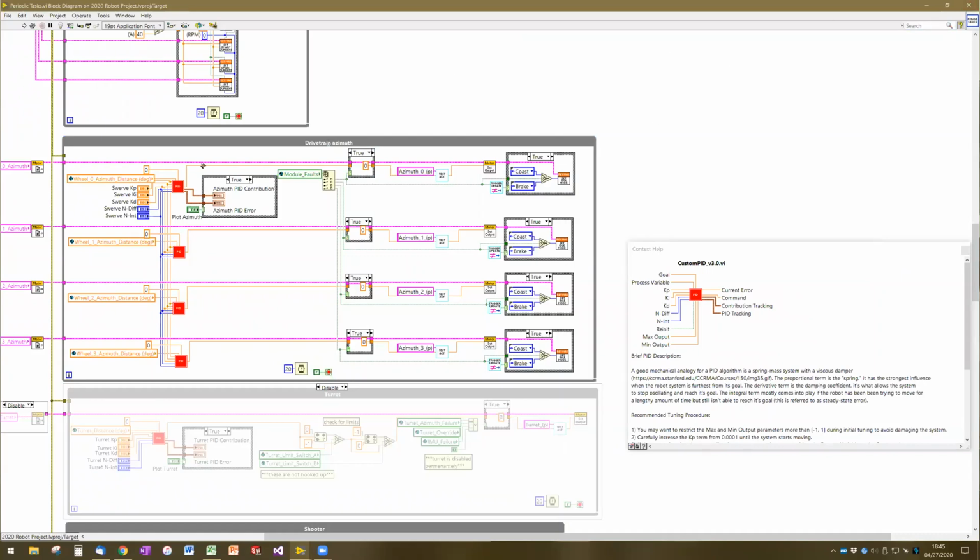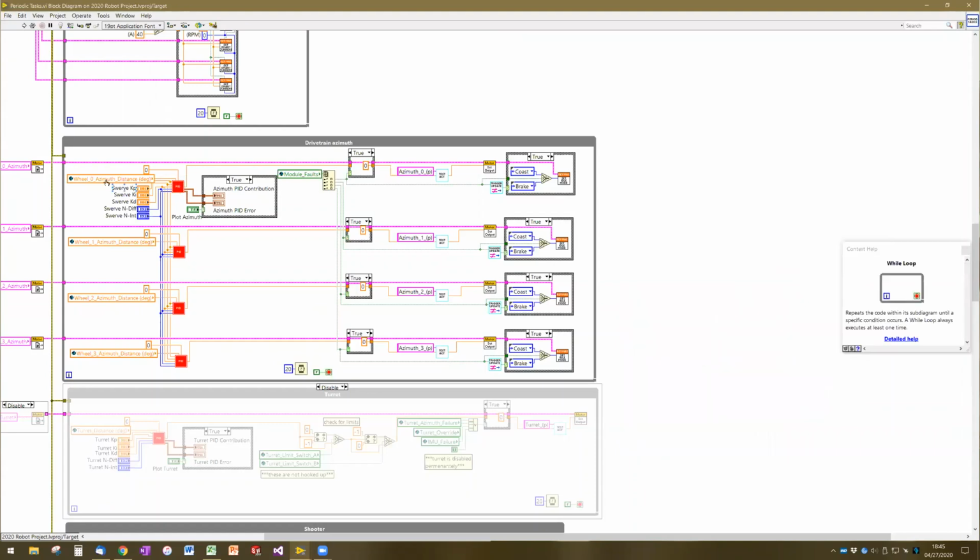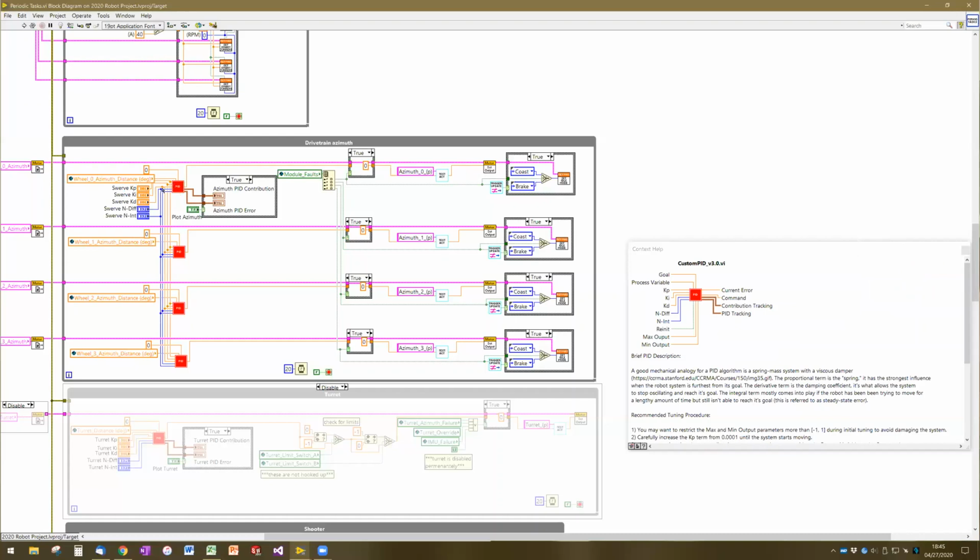Okay. Does anyone have any questions or comments about that transfer with the global variable or with the PID loop? Oh, and the other comment I should make here is to recall that we're using the PID loop a little bit opposite from how we normally do it, because what we're sending to it is already the angular distance.